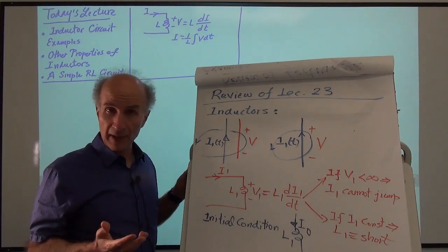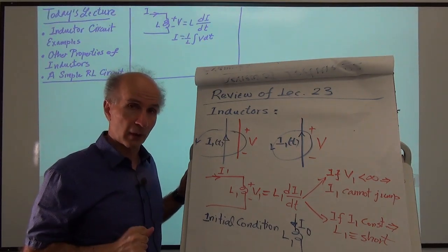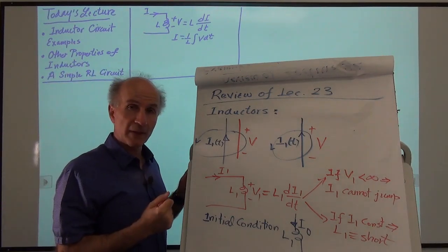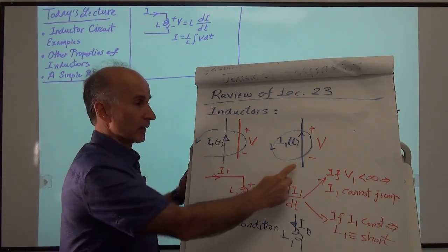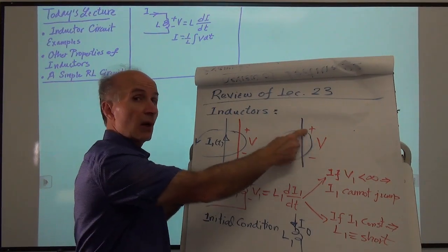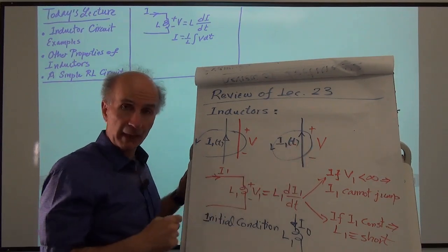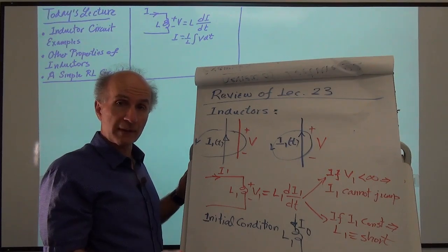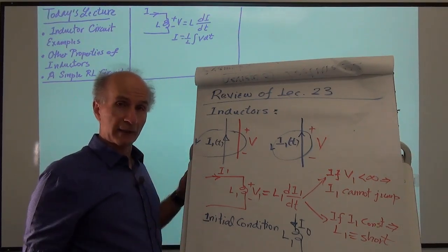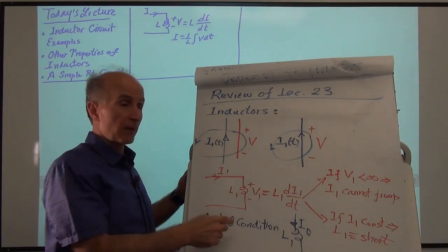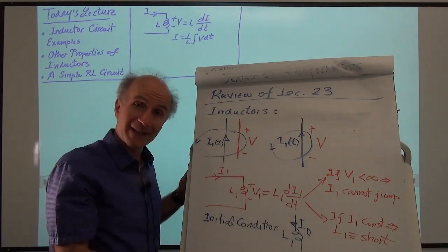So it's a fascinating effect, and it's certainly not Ohm's law. But then we tried to extend this idea, and we said that even if you have a single wire carrying a time-varying current and experiencing its own time-varying magnetic field, then that wire also must generate a voltage across it because of Faraday's law. So we would expect that a voltage will be generated here even though this wire has no resistance.